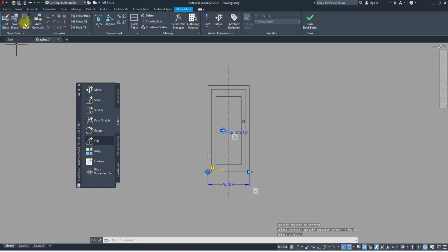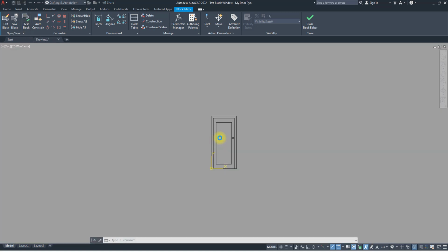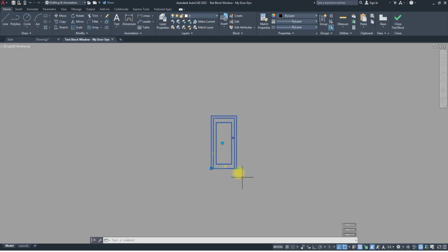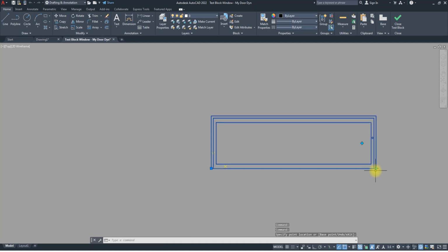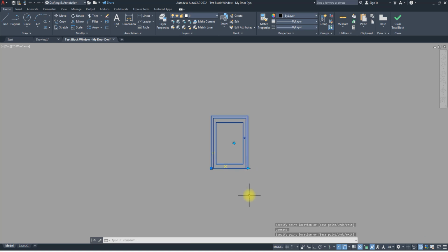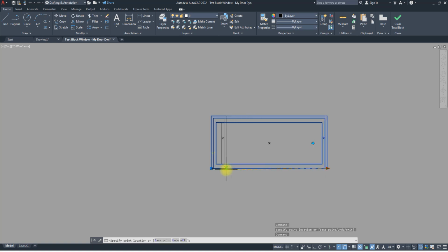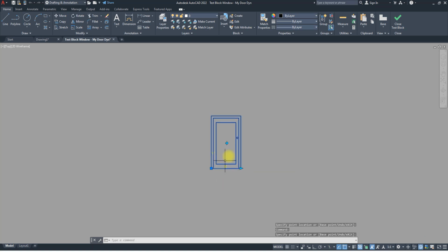So if I go and test this now, and I select this door, and stretch the width. I'm clicking stretch this all the way here. Do you see that? So I can actually use this to stretch this width, even reduce it all the way. So this is working. But you notice there's a difference between my own kind of width and the one that comes from AutoCAD. AutoCAD goes at increments. We're going to look at how to do that in a bit.